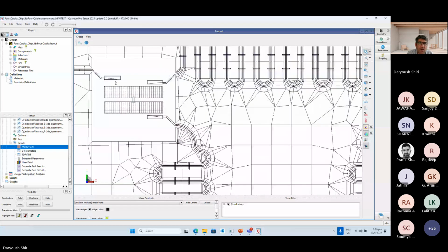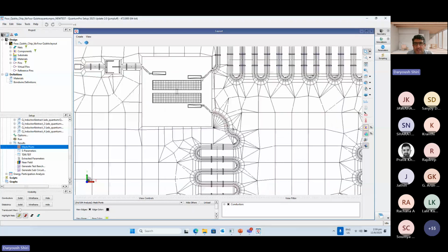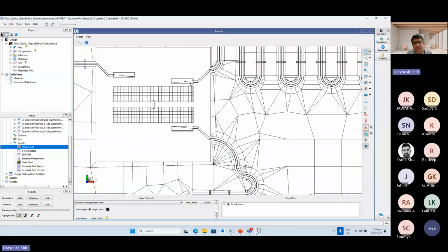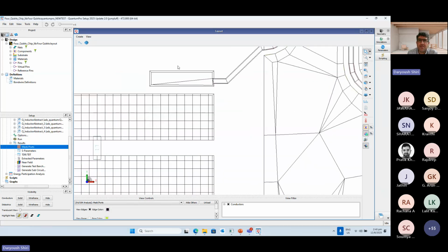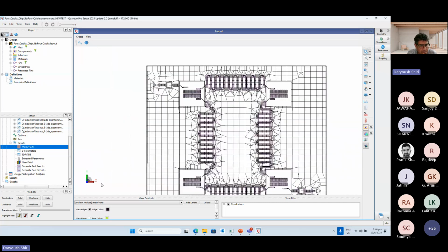If you are not happy that, like, this part is just 2 sections, then you can ask the tool to make this conductor layer have a more refined mesh, like many rectangles instead of these 1 or 2 triangles. And you can change the color or whatever here.